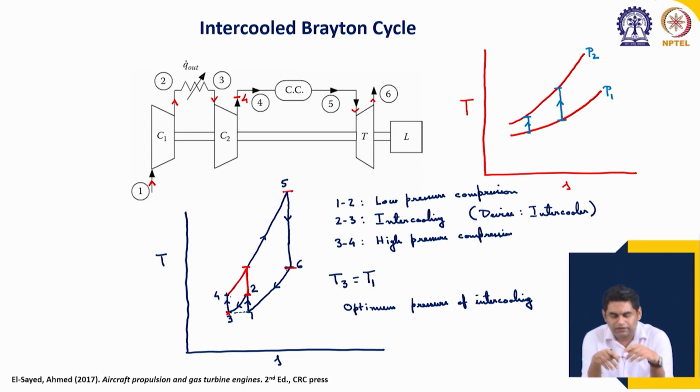On the other hand, this heat exchanger addition for intercooling is both bulky as well as it makes the cycle not self sufficient. So, you now need a continuous supply of water to run the cycle, unlike the previous cases. So, this makes the cycle depend on an external supply of water.